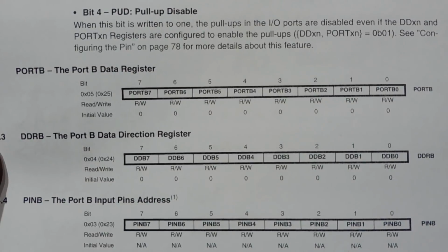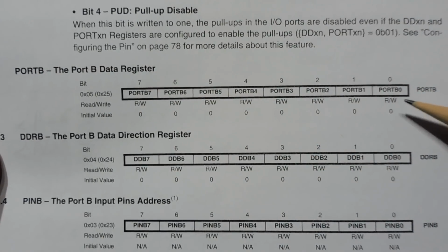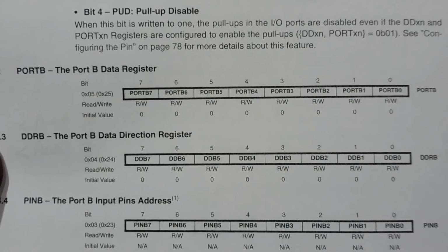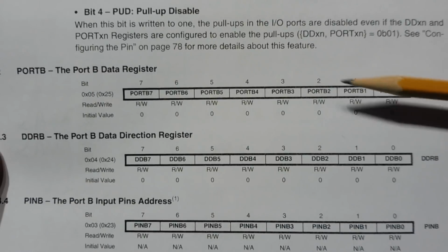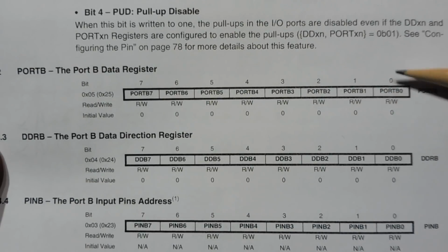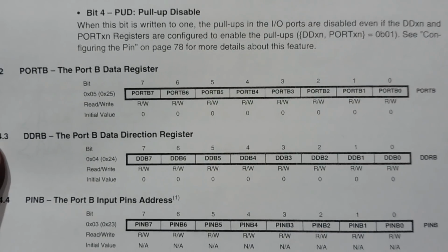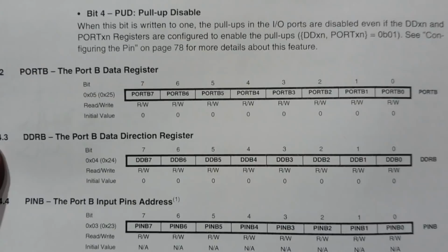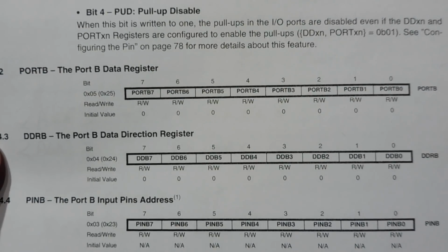So from my keyboard interactively, I could read this configuration register in binary, so it would be the same layout as you see on the data sheet. And I could go in and set or reset each of the bits independently. I could set the bit by turning it on, it'd be a 1, or I could reset the bit by turning it off, it'll be a digital 0. So I could go into the microcontroller and configure any of the registers as necessary.